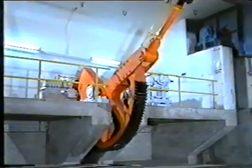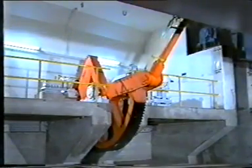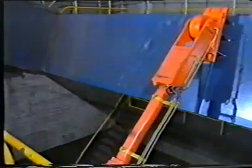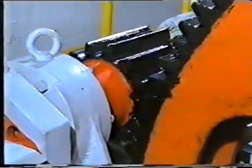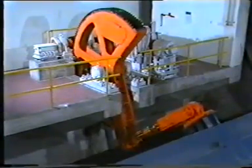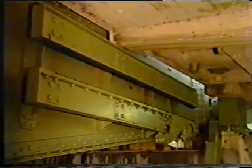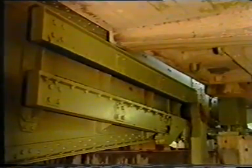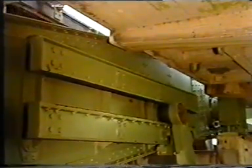The Panama wheel was originally developed by Gustav Eiffel to operate the lock doors of the Panama Canal. It consists of a circular sector with a pull-push rod connected with hinges to the sector and the bridge. An alternative for a Panama wheel is the roller slot system. A rotating crank at the end, provided with a roller, acts in a slot and moves the bridge.